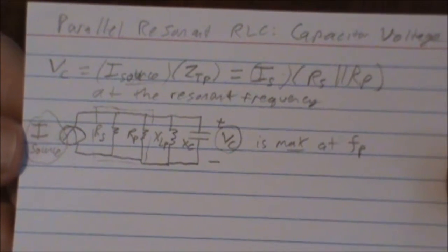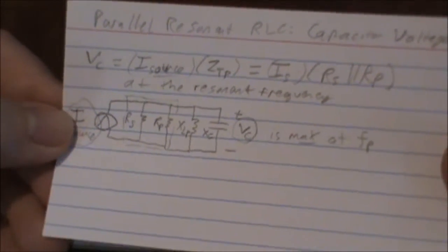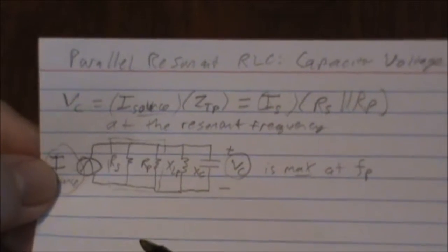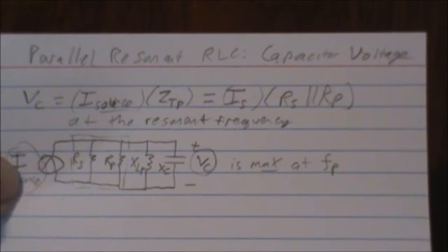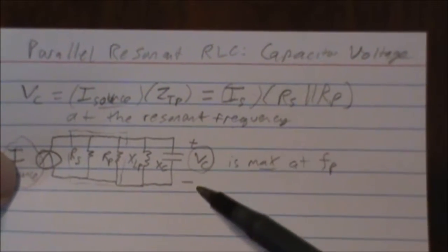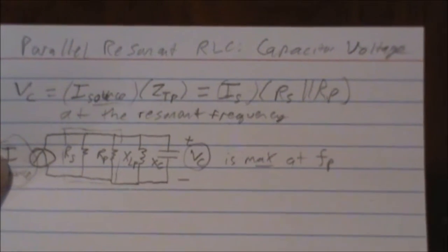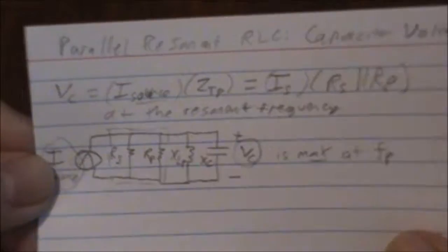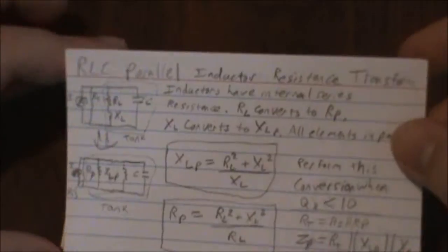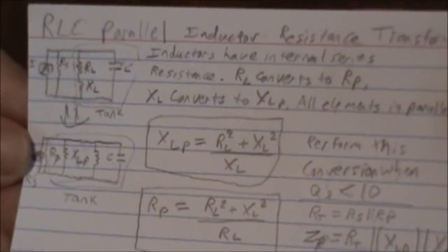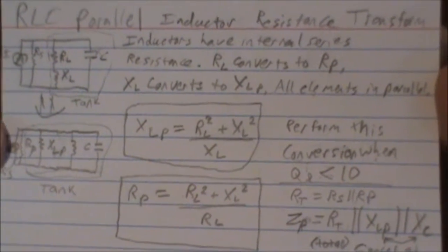And the voltage across the capacitor is, if you want to have one single measuring point for a voltage across a parallel resonant circuit, it's best to take it across the capacitor. Remember, capacitors store voltage. So this is really your best measuring point to get voltage across your parallel circuit. That's just another way to look at that formula, which we talked more about earlier, our conversion factor.